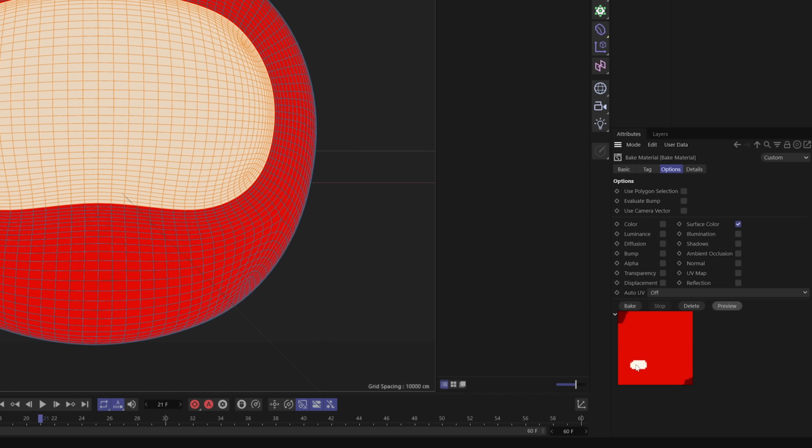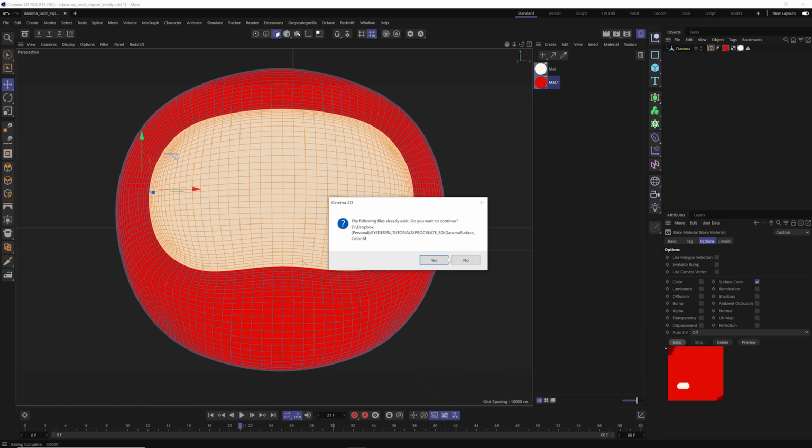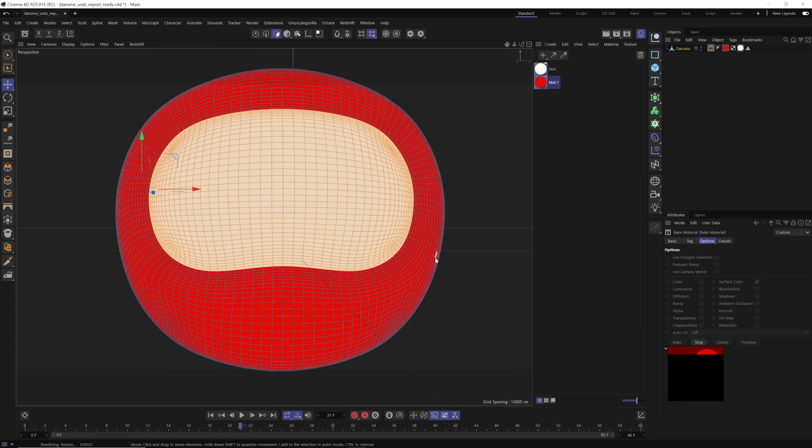And you'll see that there's our cream color, there's our red color, and there's our background color. So you can see why you want to make sure you have a different color for your background than any of the colors here, because you wouldn't know where your UV map starts and where your background ends, okay? And this is great if you want to paint in a 2D view in Procreate, which you can totally do. Like you can paint in this 2D view here, get exactly what you want, as well as paint directly on the model. So this is looking good. I'm just gonna go ahead and bake this out now, and I'm just gonna replace that image there.